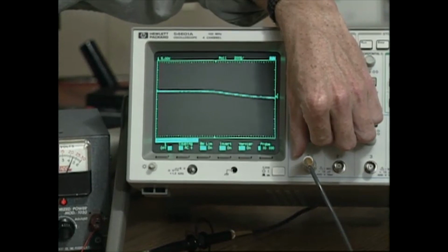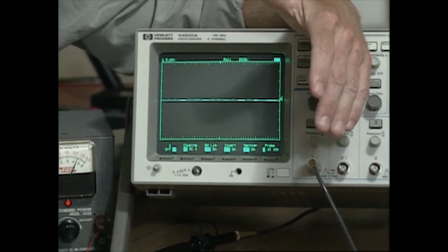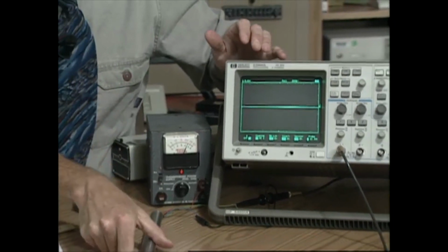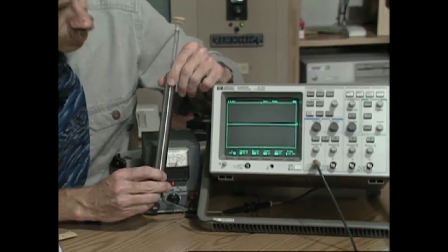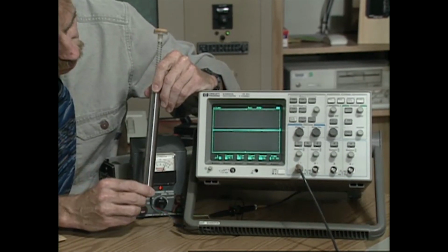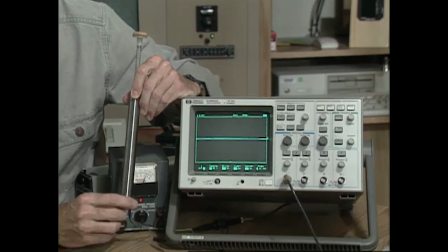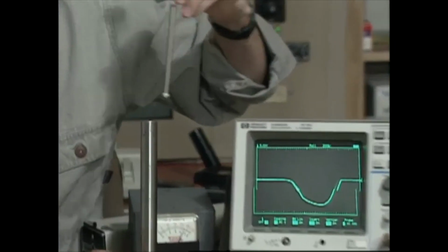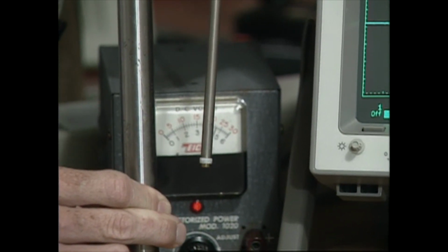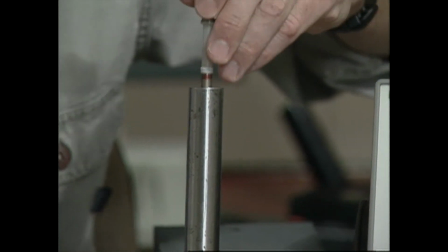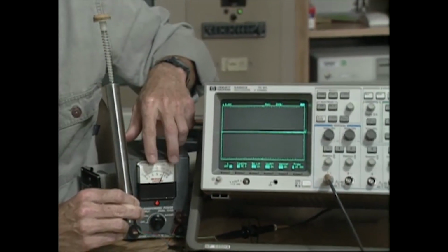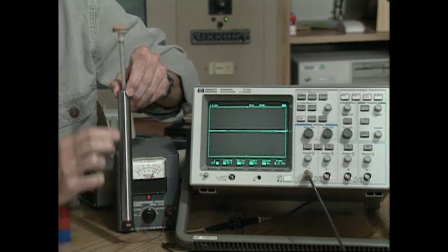Now, this is a measurement of rotary position, but I am also sometimes interested in linear position. I can also use a potentiometer there, but we can use a technique called a linear variable displacement transducer, or LVDT. What an LVDT is essentially is an inductor, which is in this metal core here. And inside the inductor is a magnetic material, I think in this case it's nickel, which goes down inside the inductor. When it does, it changes the inductance, which is measured by a circuit. The circuit is powered by this small power supply here and is actually inside the metal tube.